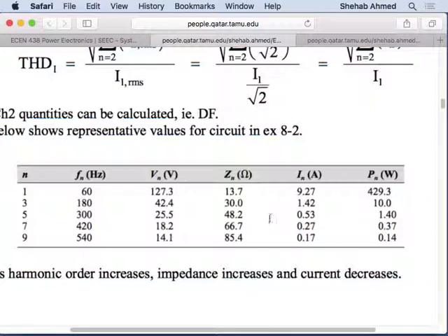So you see, the amount of power dissipated at the third and fifth is not a lot, but it exists, right? I mean, there's power at the third and the fifth components that is not very significant, but it is significant to some extent, yeah. So we would like to see a lot more of that on the fundamental. We would like to see a lot of that on the fundamental side because we would like to see a nice, beautiful sine wave on the current and the voltage.